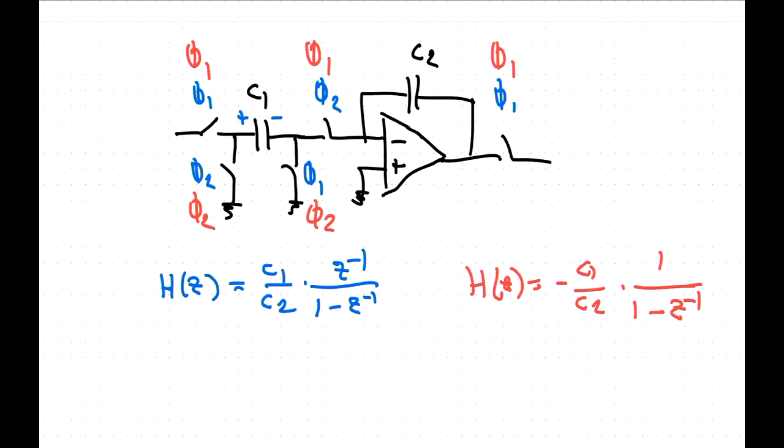So this is basically integrators. And once you can make an integrator, we can make anything, any filter. And yeah, so these are the most accurate filters you can make on chip, probably the switched capacitor filters.